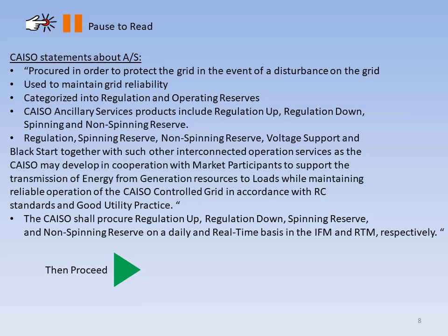Resources providing regulation are certified by the ISO and must respond to automatic control signals to increase or decrease their operating levels depending upon the need. Spinning reserve is standby capacity from generation units already connected or synchronized to the grid and that can deliver their energy in 10 minutes when dispatched.